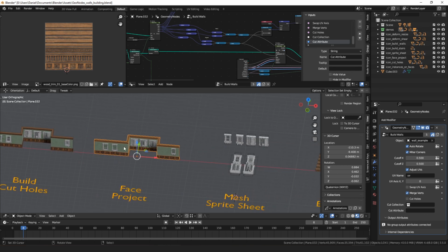So the idea was that you would make a wall and then you'd put windows or whatever needed to make holes on the wall, and then you would make a new object that was essentially a copy. You would copy the walls and the windows, and in that copy you would actually do the Boolean operation. However, that's kind of a pain because then you can't see the final result on what you're editing, because it doesn't actually make a hole in the wall there.